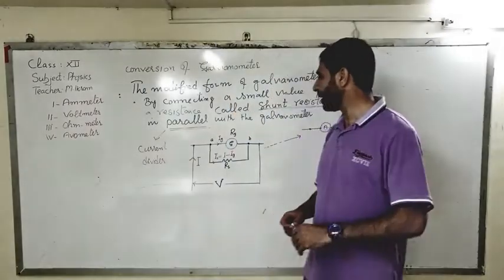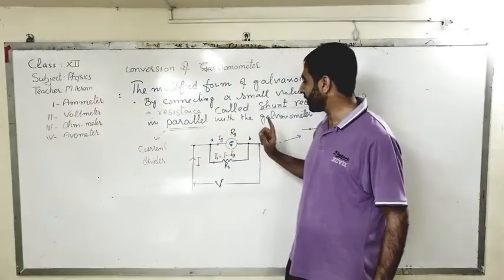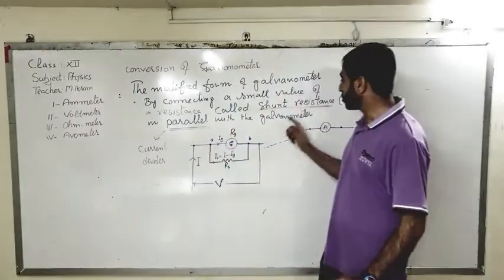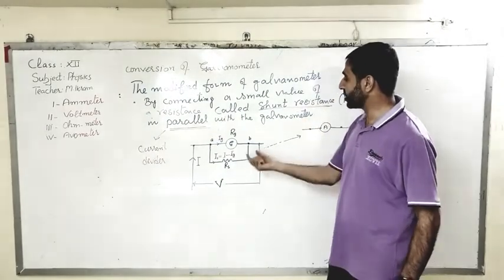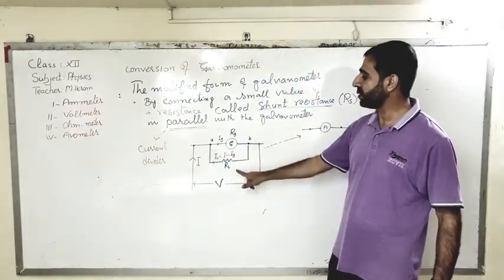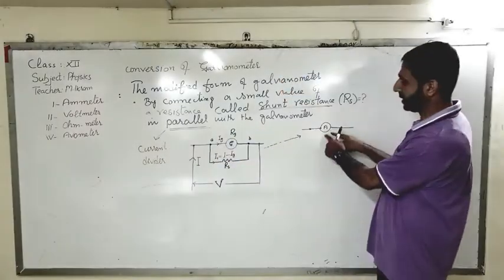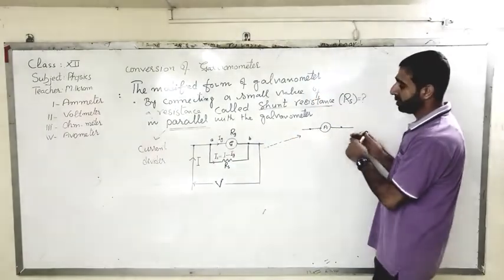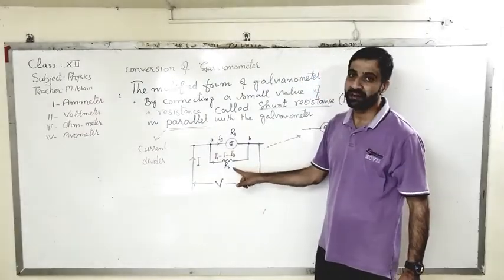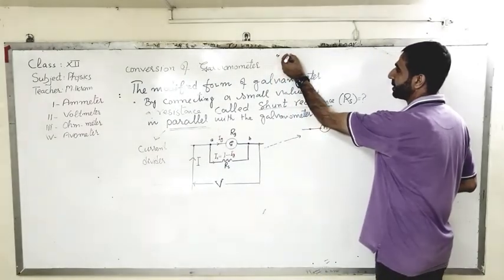Now you see here, as I told you, we connect the ammeter in series within the circuit to measure the current. So we kept the shunt resistance, or we have chosen a resistance, of very small value. Why? Because when you connect it within the circuit, the ammeter, this is the interior structure of the ammeter. You know that when there is a large current, since current always chooses the path of least resistance, this is the basic principle of this chapter, right?